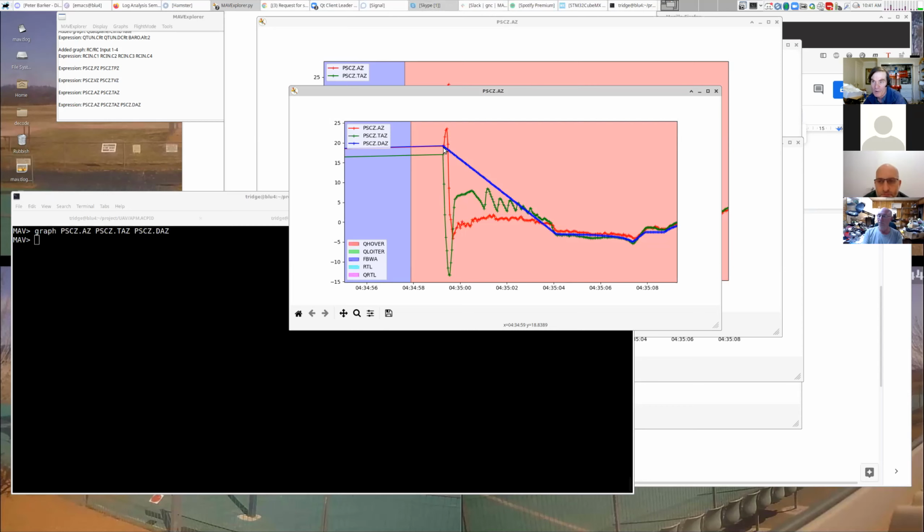And it says, we want to start with that point and then start the controller. But look how long it takes to bleed this off, right? So it takes, what is that? We're starting at 34.59 and we're ending at 05. So we've got 5 seconds before it bleeds down this desired acceleration, okay? And so that means that initially the controller is going to be aiming for this acceleration, and it's going to be putting on this target acceleration, dragging it up. So here's the actual acceleration, and it's dragging it up. The target is over the actual and saying, go, go, go, I want to accelerate, right?